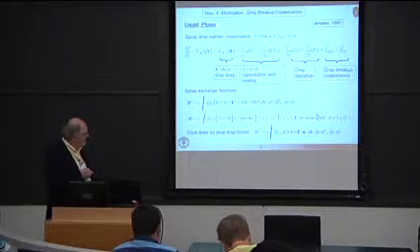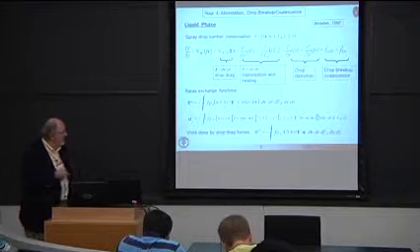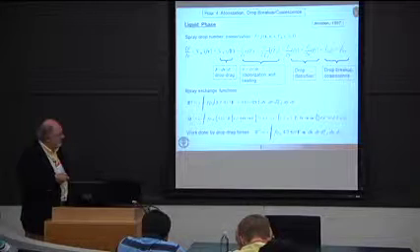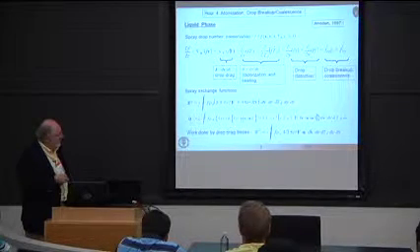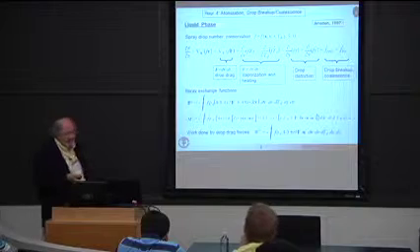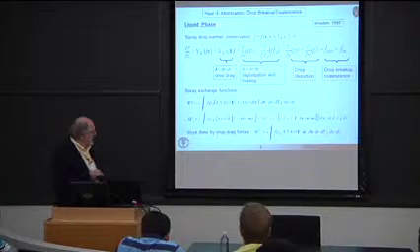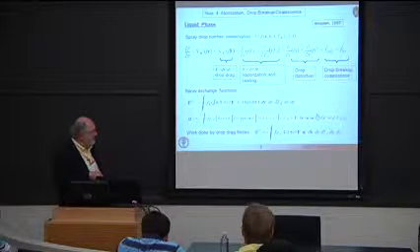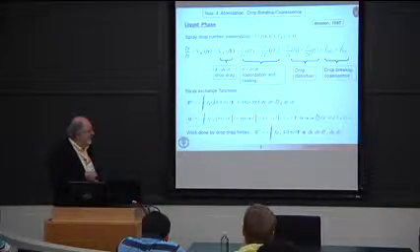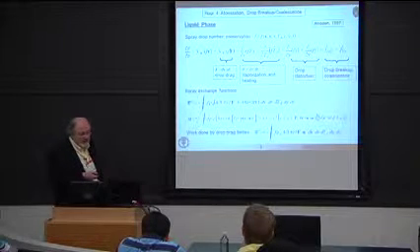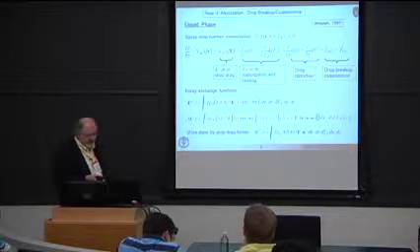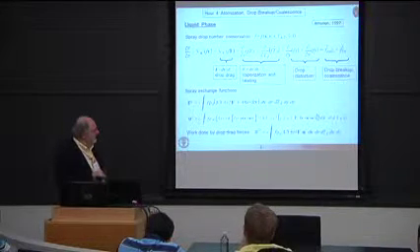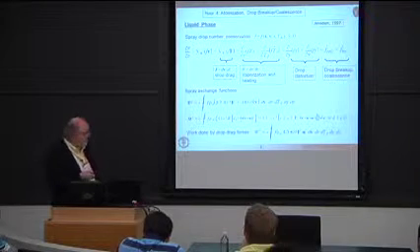Similarly, if we're looking at the contribution in the energy equation due to the spray, as the droplets vaporize, here's the surface area times the rate of change of radius, they carry with it a change in the kinetic energy and the internal energy associated with those droplets. Here we have a change in energy due to the change in droplet temperature. As you might expect, the droplet temperature changes again because of heat transfer with the ambient gas, and that needs to be accounted for in the source term.